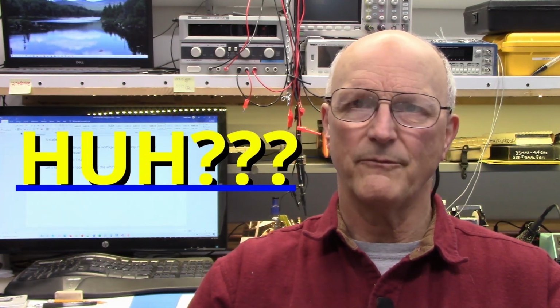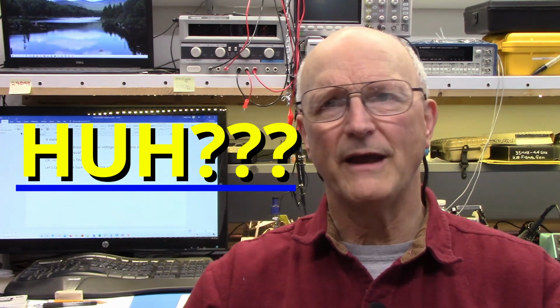Now, this law was named after Gustav Kirchhoff, a 19th century Russian-born German physicist. Kirchhoff's Voltage Law, or KVL, was announced in 1865 along with his first law. It states that the algebraic sum of the voltages around any closed loop must be equal to zero. Well, what does that mean? Let's take a quick look at this on the whiteboard to find out.